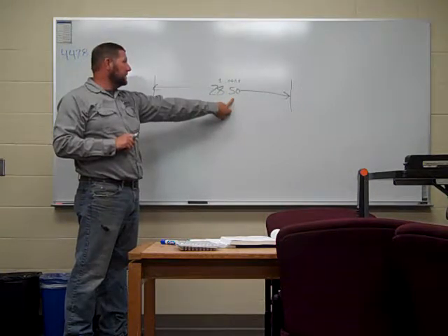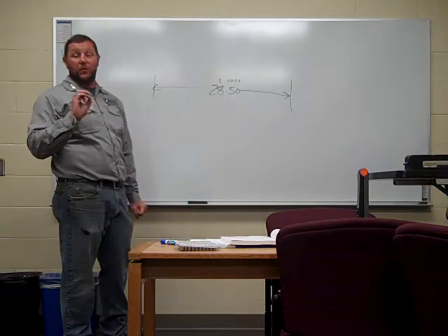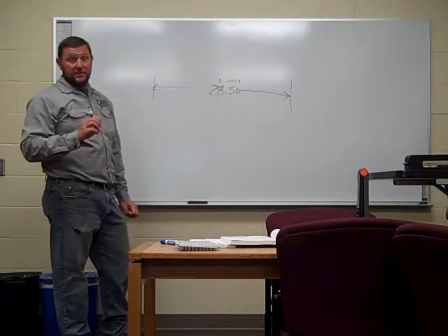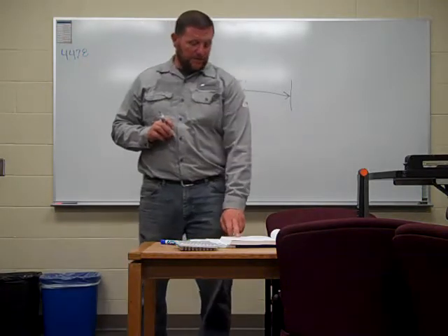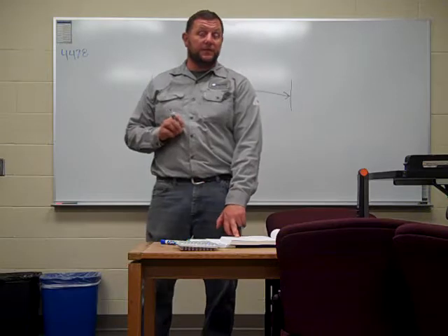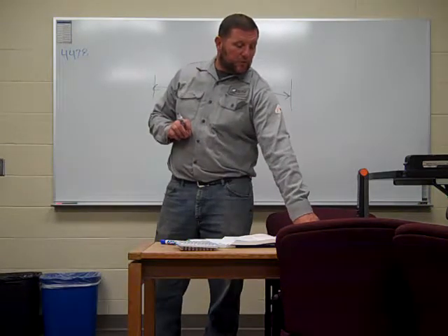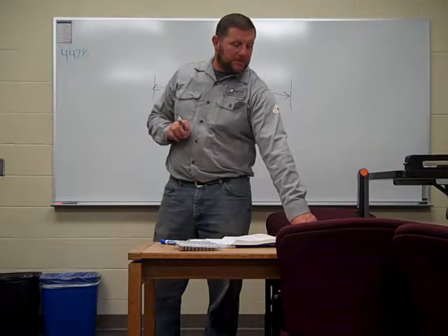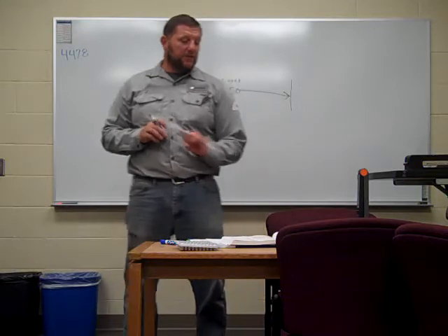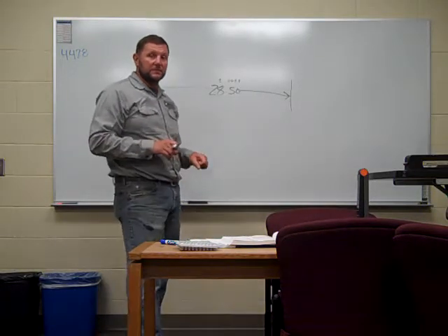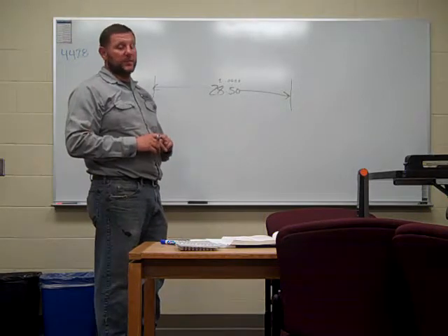It's called explicit tolerance. That tolerance is directly used with that dimension and only that dimension. That's the example you see down here in figure 9.4. They're giving you the range that that piece can fall within. As you turn the page, you can see it. You have 2.50 plus or minus 0.06. That's giving you the exact tolerance. You do not use the general tolerances. You use the tolerance that is given directly to that dimension.